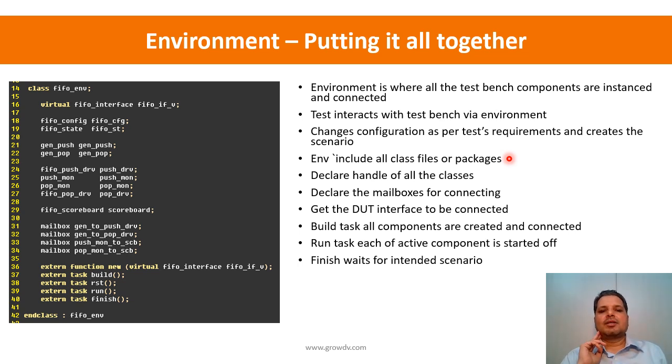Once we have included the packages or the classes that we need, we have access to them. So we are now declaring a FIFO interface. If you look at it, there is no modport information, so it's a complete interface that we are getting, but it's a virtual interface. Anything in the class world will be virtual. You can think of it like a variable or a reg type, whereas the actual interface is very loose, like a wire or a static type of data.